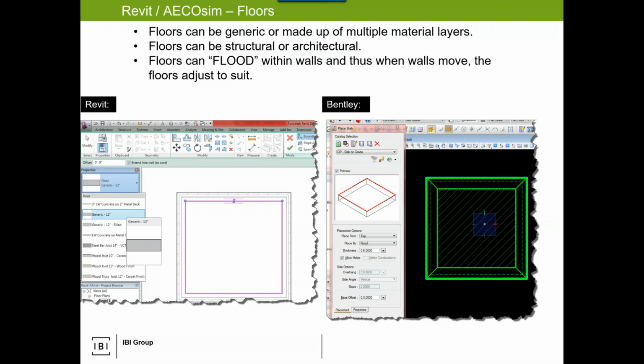Again, generic versus non-generic. If you remember when I showed that slide, BIM is nothing more than a component plus information. The very fundamental piece of information here is I am placing 3D geometry knowing it is a slab. I could then include, like the example on the right, that it's a cast-in-place concrete slab on grade.